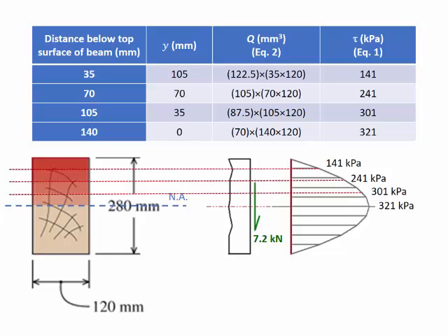Note that the distribution of the stresses below the neutral axis will follow, because this is a cross-section that is symmetric with respect to the neutral axis. But I want you to note that the distribution of the shear stresses follows a parabolic distribution with zero values at the top and bottom fibers and the maximum value at the neutral axis. So always remember that in the shear formula, VQ over IB, V over IB is going to be constant for the cross-section, so the only thing that varies within the cross-section is Q, and Q has a parabolic distribution along the depth, with a zero value at the top and at the bottom, and maximum at the neutral axis.